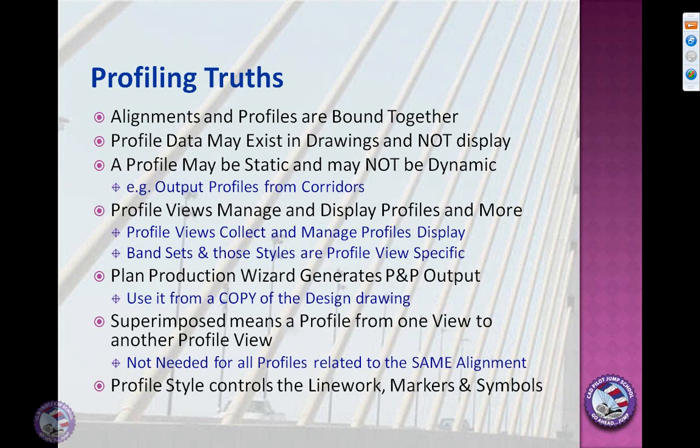The other issue, and one of the classic things, is I need to show the flow lines from my roadway design, and I'll point out something in this drawing: they may not be dynamic. There are a number of issues where a profile may not be dynamic, like this design profile that we're working on. My service profile also may not be dynamic, and I may not want it to be, for attachment reasons and all those other kinds of things.